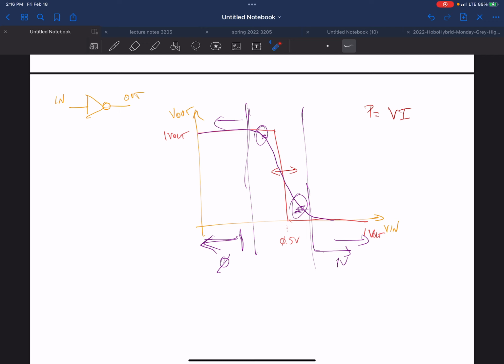In some sense, you can do better if you use older processes. As you'll see in the slides, a lot of what causes this is just the nature of both NMOS and PMOS being on, but some of it ends up being second and third order effects with aggressive process technologies. Are you familiar with NMOS transistors, the square law model, saturation, linear mode?